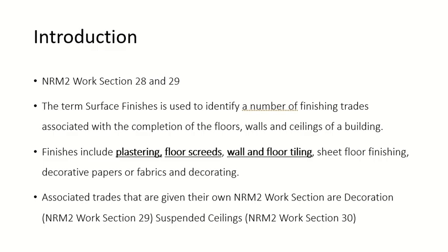If you remove this, you will still see the concrete slab. Somebody who is at the first floor, if they remove the ceiling for the guy at the first floor, I will not fall down. I'm not standing on the false ceiling or the suspended ceiling. I'm standing on the real slab. So this is why it is part of finishing.